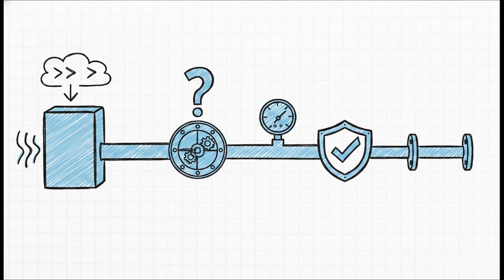Question 2. What is the valve's mechanical fail-safe action, and is there a manual bypass installed? Question 3. If the control valve fails wide open or the manual bypass is inadvertently opened, what pressure actually reaches the downstream piping system? Question 4. Is there an independent certified relief device actively protecting the piping before that critical pressure is reached? Question 5. Only if the answer is yes, you may confidently place your spec break right after the valve assembly, stepping down to the lower piping class.